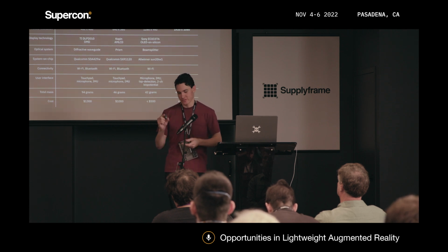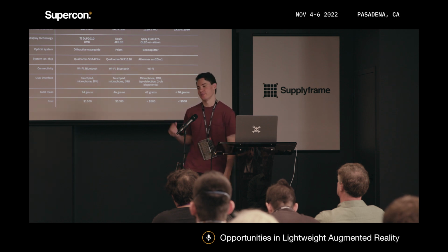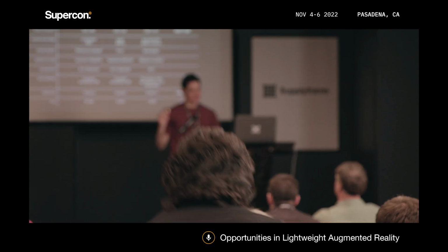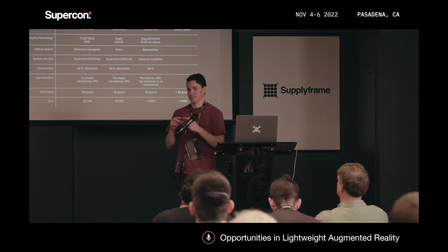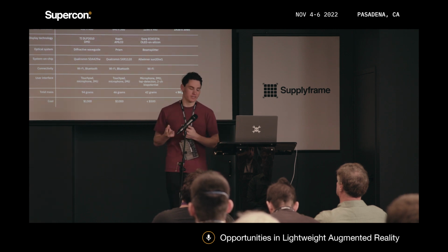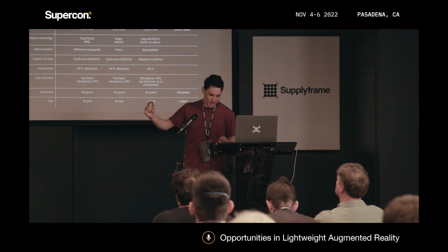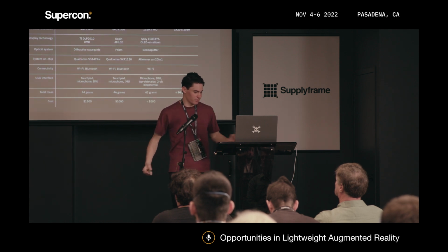So this design that I'm currently working on goes a bit farther with the electronics miniaturization. So it's going to have a high density interconnect PCB with the laser drilled micro vias, via in pad, and all of that fun stuff. These designs I've done so far have really been getting to the very limit of what you can do with plated through hole and traditional mechanical drills, without blind and buried vias, and you essentially just run out of space for vias. I didn't mention, but this is a 6-layer board, the one that I designed mostly in 2021, and the earlier prototype that I showed, those were 4-layer.